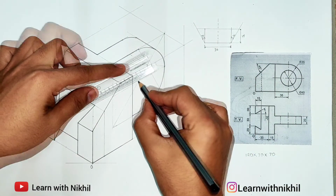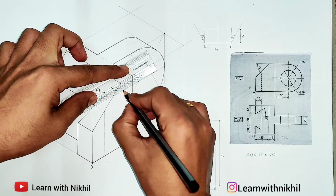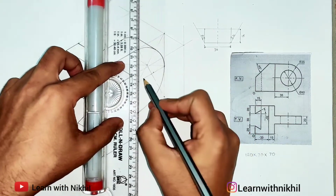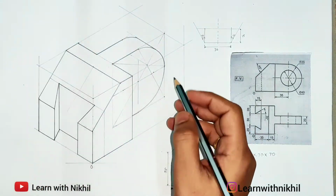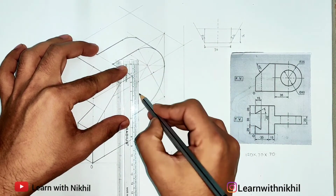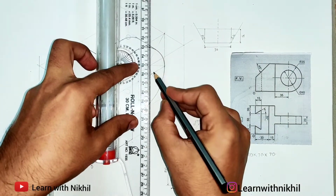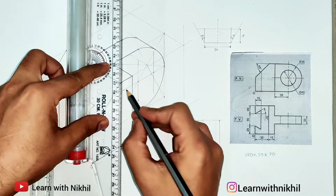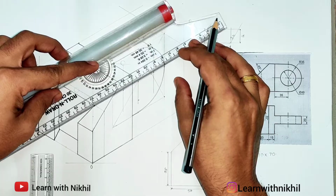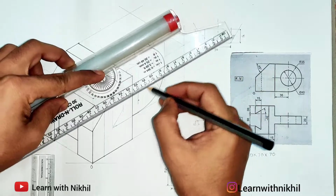Now from here 20 millimeters on this line, 20 millimeters on here, taking this as the reference line. From here drawing a line. So from here 20 millimeters above and 20 millimeters below, drawing a rectangle. So this is how we have drawn a square of side 40 millimeter.